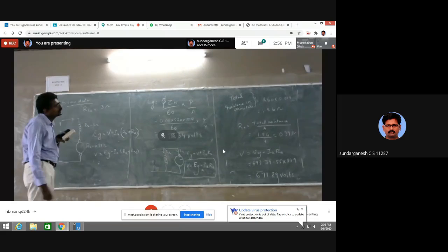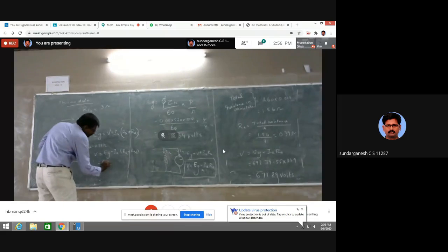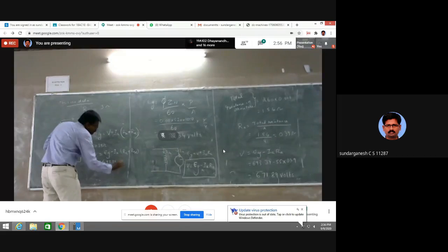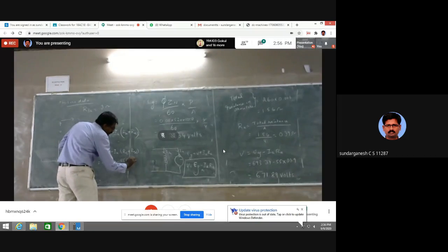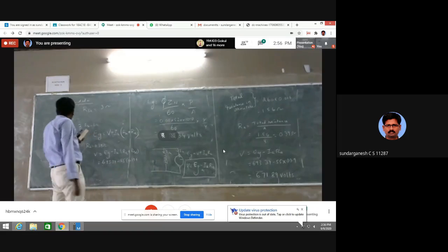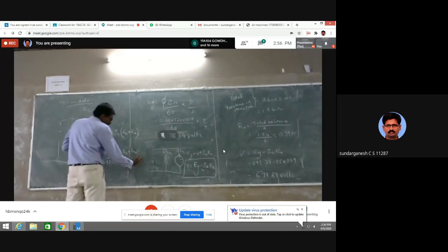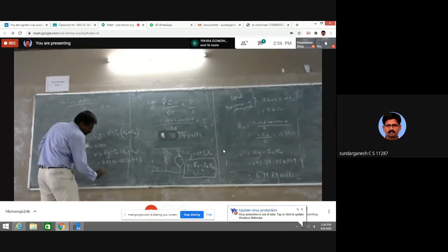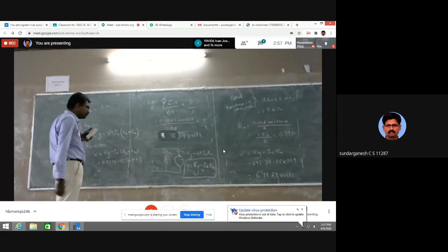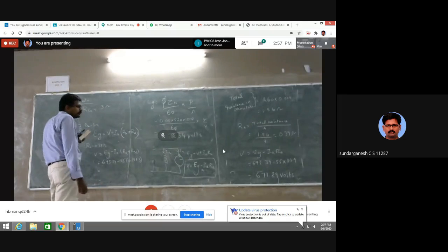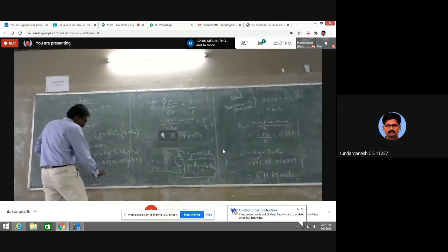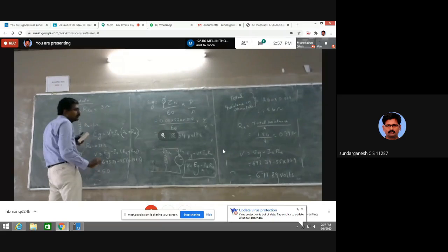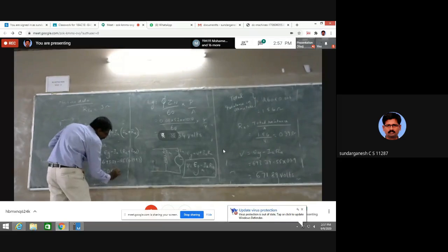EG is 693.34, IA is 55. 55 into (0.39 plus 3 ohms), that value minus 165. So it becomes 506.89 volts.